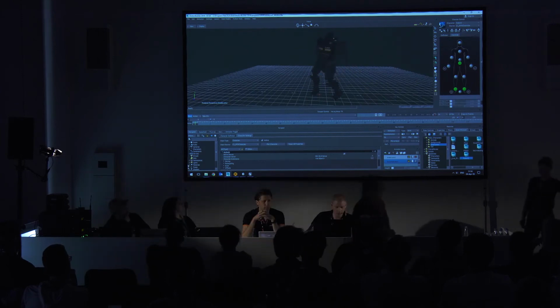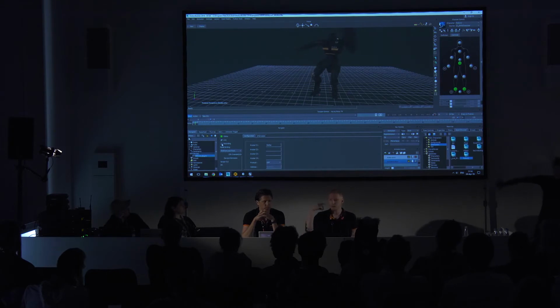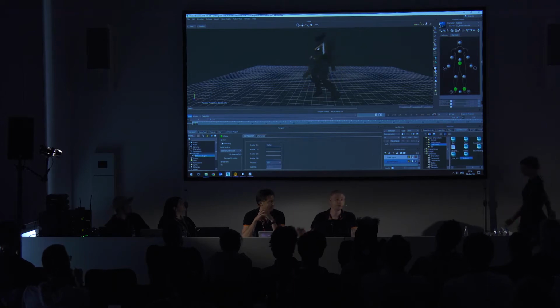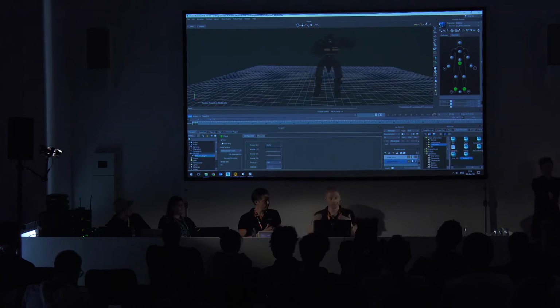Now the great thing about our plugin is that it does not only stream, it also gives you the capabilities of actually recording the data directly into MotionBuilder, so it will just make you new FBX takes every take you record it. However, I do always advise to do your recordings in the MVN software as well, simply because we always record raw data. So it's just sensor data that comes in, and we always calculate that from within the file.